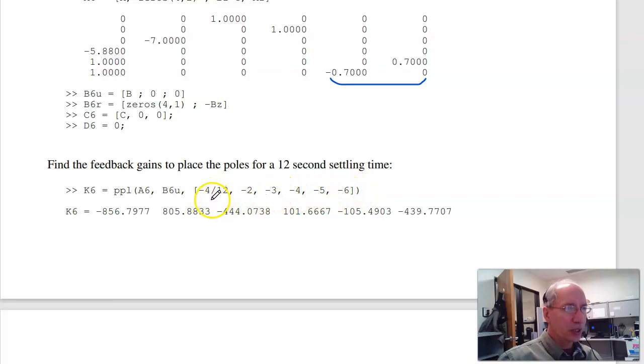When I do that, the first 4 gains are Kx. The last 2 are times my dummy state, the servo state. So this is your Kx, and here's your Kz. I can check the linear system, form the closed loop system. In this case, I have to use our step 3 function because MATLAB doesn't have the input to a sine wave input. I have to create one. This is for an arbitrary input.